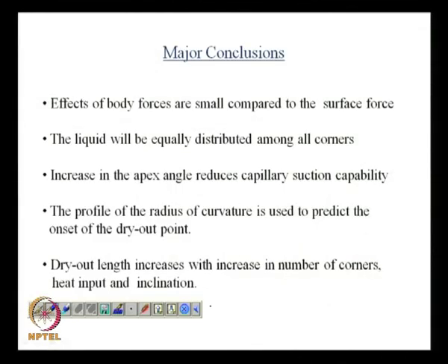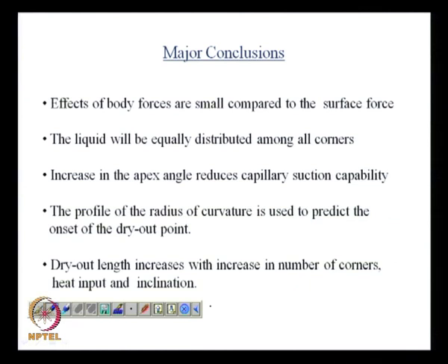And finally, before I end, this is the summary of what we have studied so far. The body force is rather unimportant compared to surface forces, and since the body force is unimportant, the liquid is going to be almost equally distributed at all corners, which is something you definitely want. You do not want only part of your heat pipe to be operational, while the top half does not take part in the heat transfer process.